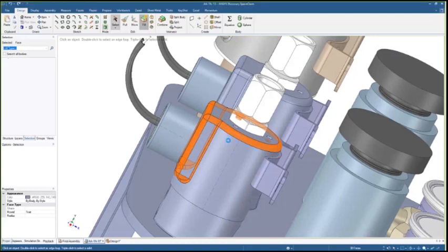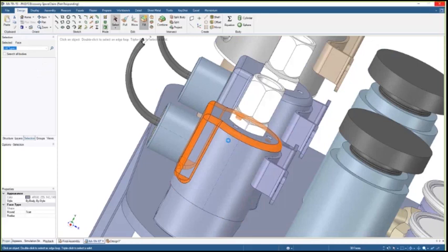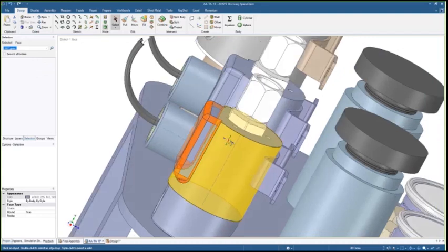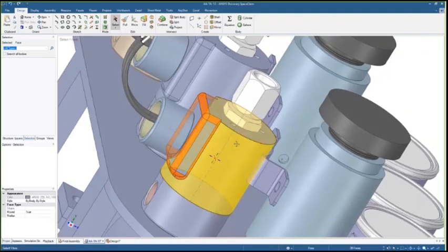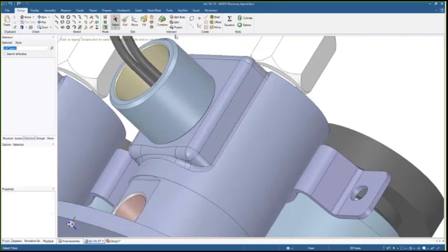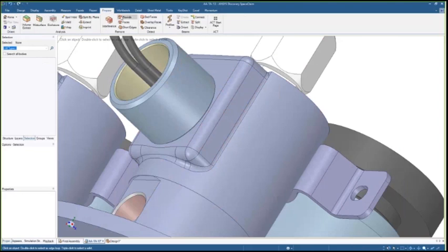Now, sometimes the geometry can be pretty complex, and it may have issues doing so. Sometimes we just need to give it some time, and you'll see that it was able to remove some, but not others. The main reason is when they intersect. Sometimes it can't figure out intersections like this. So we have a dedicated tool to help with round removal in this scenario.